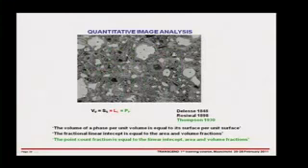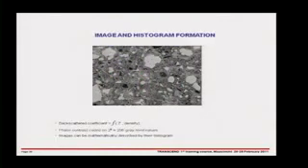We have this very reproducible contrast, which can be done by a computer. If you do optical microscopy, for example, on clinkers, then you have to have an operator who has to sit there, look at various points, and identify what phase they fall in, because the contrast isn't reproducible.